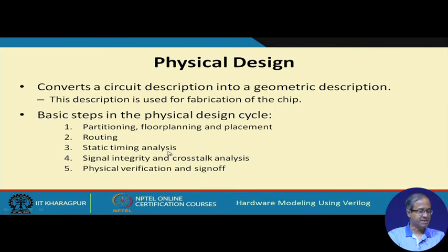Static timing analysis, extremely important in the modern day context. After I have completed placement and routing, I need to check whether my design is meeting my timing constraints or not. If not, I may have to go back and change these things. Signal integrity, crosstalk analysis, these are related to timing analysis, these are also very important. And when everything is fine, I see that everything is meeting the requirements, then I complete my physical verification process and do a step called sign off. Sign off means I am satisfied with my physical design. Now, I can proceed to fabrication. Okay. Fine.